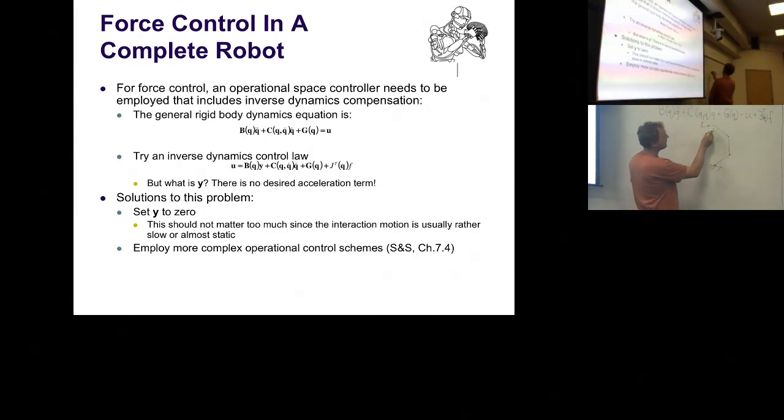It's just this force times the moment arm to this degree of freedom, which is F cross product with this moment arm, let's call it A1. For the next joint, same story, this now becomes my moment arm, A2. F cross A2 is the torque which I have to generate.